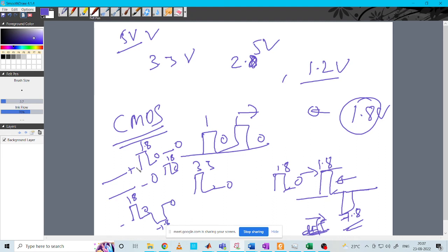Yes. So in both the positive and negative line, you are just feeding the positive voltage. But when you are taking the difference, you are getting something like this: 1.8 and minus 1.8. You got it, right? What I'm trying to say? So it is based on the differential CRO. You provide 5 volts here and 0, the CRO will detect 5. You provide 5 volt here and 0, the CRO will detect minus 5. Or the multimeter. So with respect to what you are measuring, that is important.